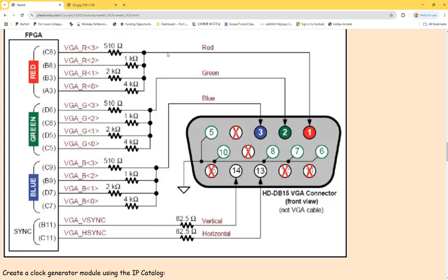So this one has the least because this resistor is so big, it's going to drop most of the voltage and leave only a little over here, which is still 300 ohms. So this contributes the least. So in that case, because there's only one rod for each signal line, eventually it's giving you an analog signal at each rod. So the VGA port is digital before the rod, but eventually when it arrives at the rod, it's an analog signal.